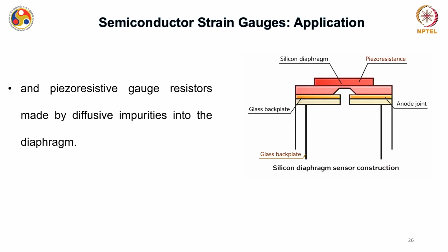These impurities can be diffused to these points in various ways of doping silicon. You have two general methods for doping silicon: you can dope by diffusion, and you can also dope by ion implantation. Diffusion is mostly a temperature driven process where you have a thermal gradient and a concentration gradient, and because of these, the impurities diffuse and get implanted.